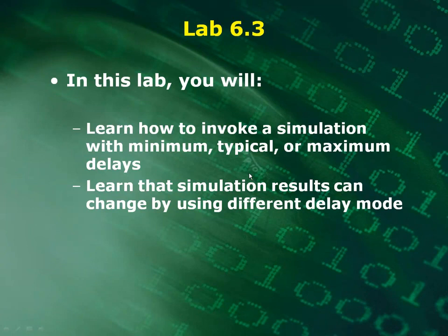So in Lab 6.3, I want you to learn how to invoke a simulation with min, typical, or max delays, and learn that simulation results can change by using different delay modes. And that's the end of our class for today.